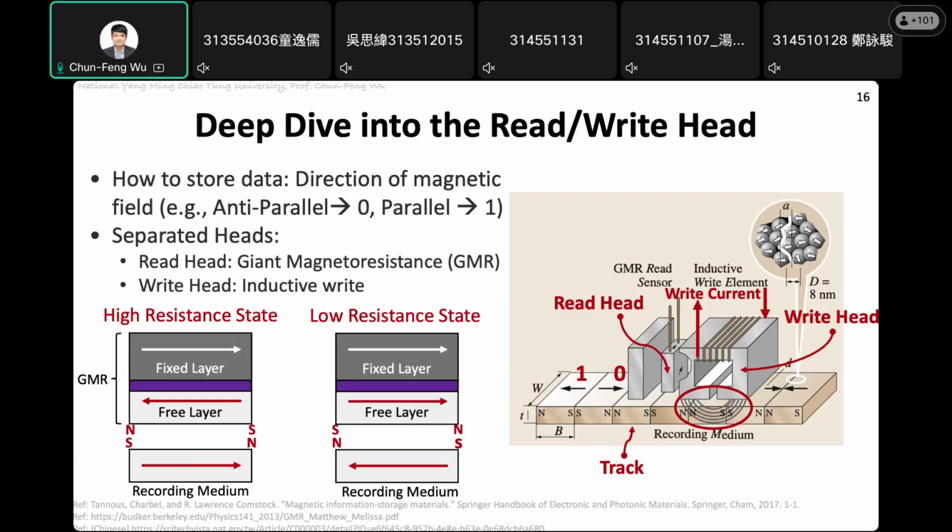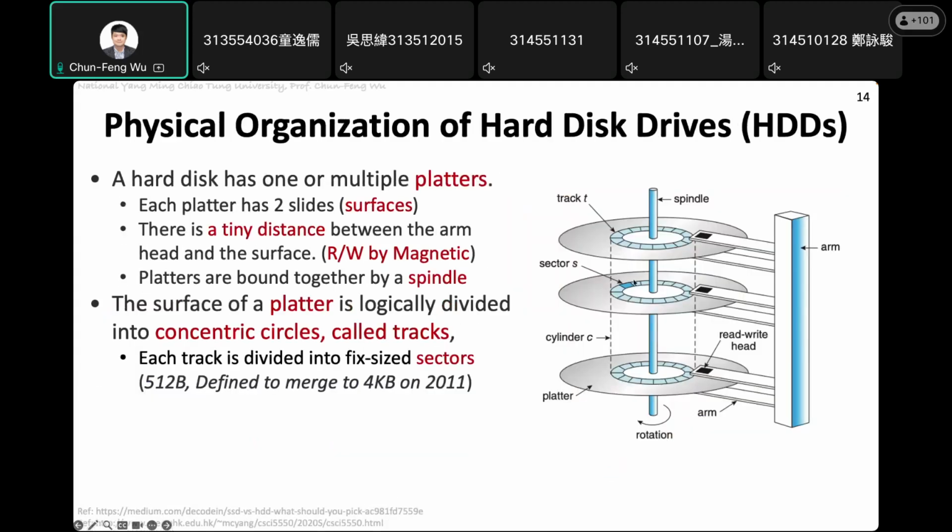the capacity of the hard disk drive is quite hitting the limitation now. Because now if you are going to buy a hard disk drive, you can get around 8 to 12 terabytes, right? But it is hard to shrink the recording medium to make it more dense, because there are effects. If you make it denser, then the write current, the write head, will affect the neighbor. Okay, and also the spindle, the number of plates on it, will also be limited by the